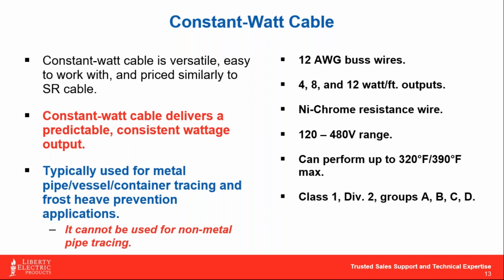However, you do not want to use this one against anything PVC based because, again, there's nothing there to back off that heat, and eventually you will probably run into some problems with it either embedding into the skin of a PVC based pipe. Certainly we wouldn't want to see it melt through, but that's exactly why we don't typically recommend anything with constant wattage on PVC based materials.